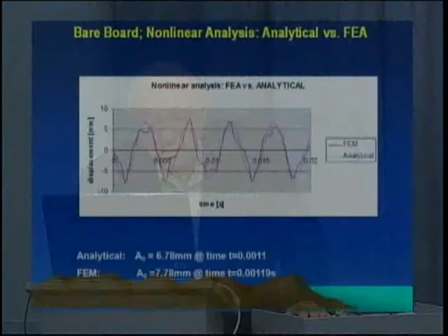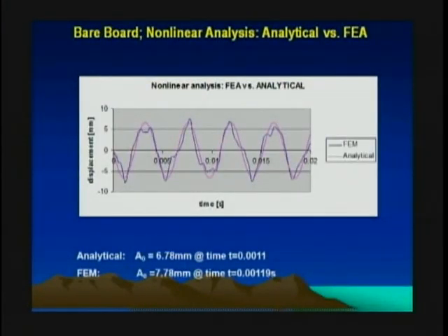You see some impact of the higher modes of vibrations where you see just deviations from nice and smooth cosine or sine curve. But in general, if you consider the analytical nonlinear result for the vibrations and compare that with the finite element, it's excellent agreement, which indirectly also indicates that it's okay. You can get away, as I mentioned to you several minutes ago, without considering high modes of vibration, which is good news.